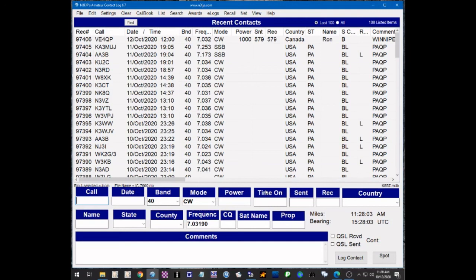So if you have even more radios, and let's say one's an Elecraft K3 or maybe a Yaesu radio, you just put in the proper configuration for that, save the settings, use Control X, and it'll scroll through the various radios that you have interfaced with your computer, and your log program can select the one that you're currently using to log contacts with. So that's about it. That's probably the first thing I would recommend doing. Once you get a log program up and running, get it interfaced with your radio, because there are other very handy things that you'll be able to use that for later on, other than just pre-filling your band and mode, and we'll get into that in some of the next videos.